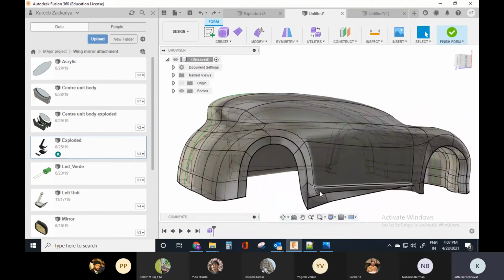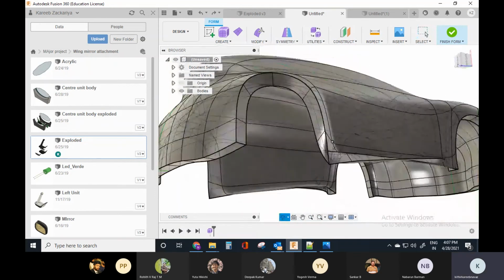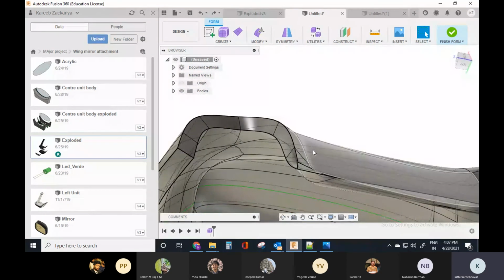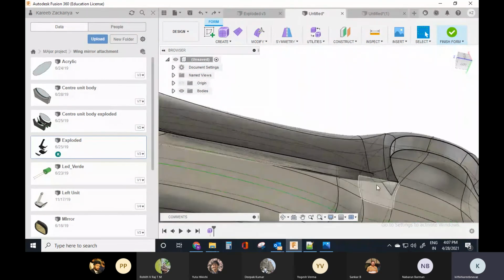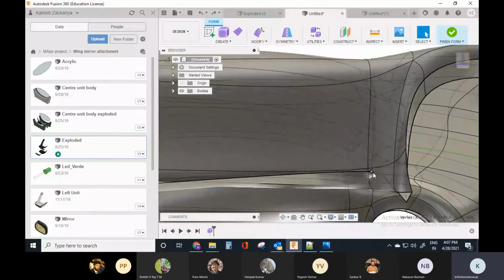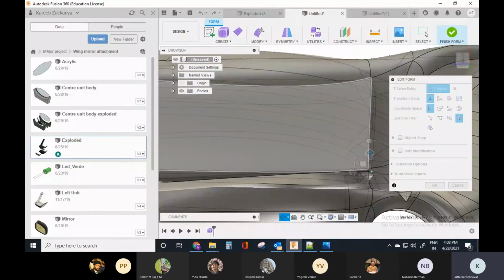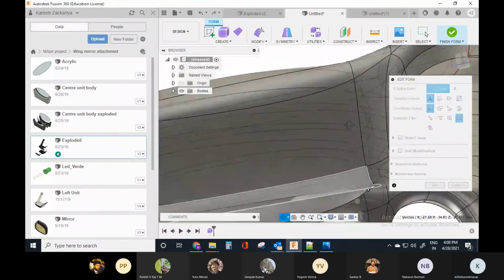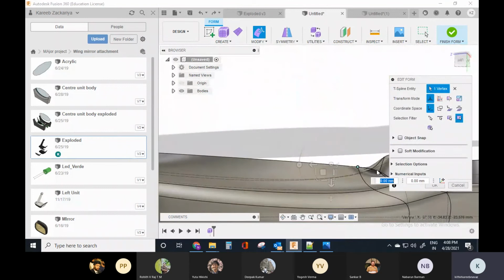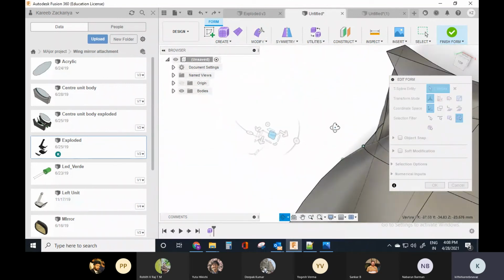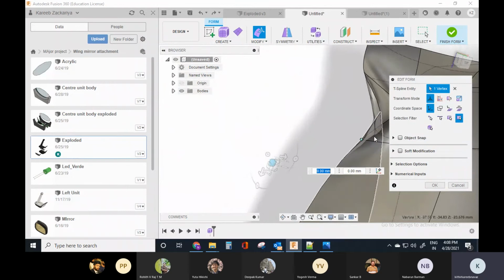To convert. So these things will happen once you do this thicken option. Some T-splines will fail, for example here. So you can go back, edit form, and somewhere you'll have to adjust and see where these T-splines are failing, and then you go back to design.